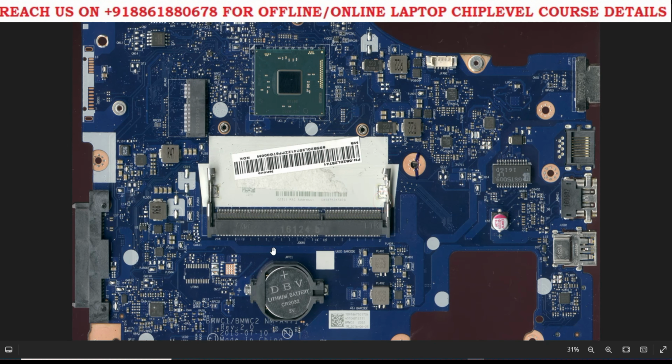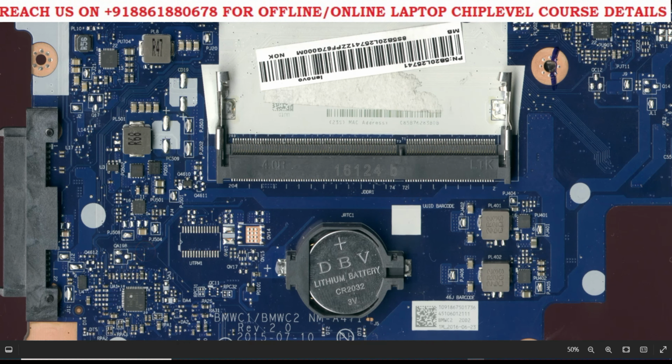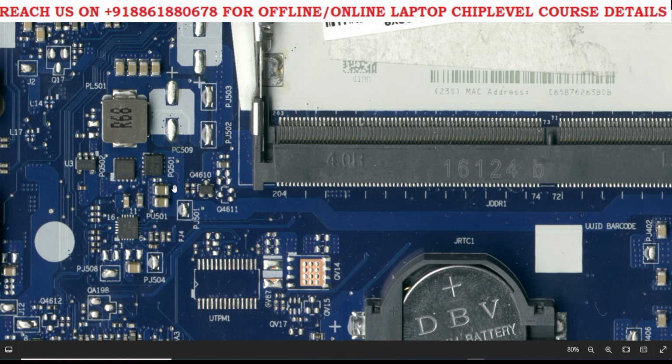See, the main thing is we are giving 19.5 volts. Here the 19.5 volts we are giving to the high MOSFET. Here are the high and low MOSFETs. The drain will receive 19.5 volts, but the source will give some voltages, and the coil output will give the appropriate voltages. For example, let us check, it's a 3.3.